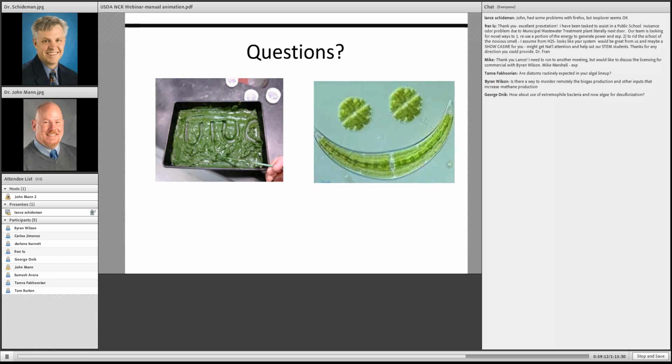And if you really want to have a no-smell wastewater treatment plant, you just have to capture that gas, put it through an activated carbon bed, and then let it out. So it's feasible. The big advantage here is that you would have some additional revenue that could help pay for that collection and treatment effort. Whereas with the current system, it would be a cost that you're spending, but you're not getting any benefit out of it. And so I think that would be the primary advantage.